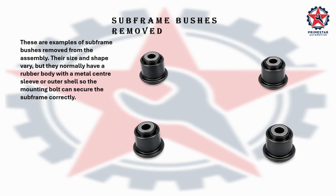These are examples of subframe bushes removed from the assembly. Their size and shape vary, but they normally have a rubber body with a metal center sleeve or outer shell, so the mounting bolt can secure the subframe correctly.